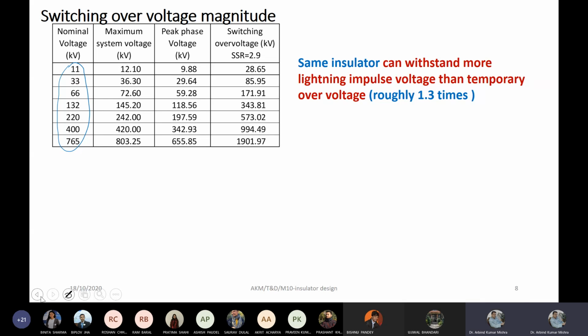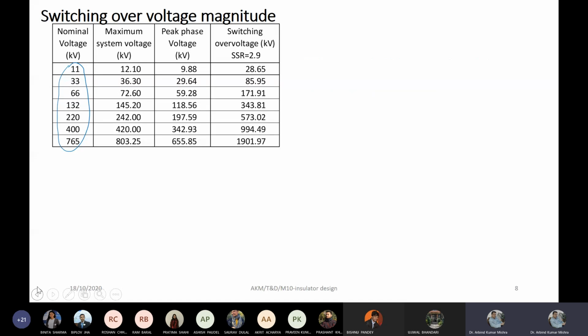as a multiple of the system voltage. So how do we calculate it? For example, for 11 kV, just multiply it by 1.1 and you will get the maximum value. Then you have to find its peak value. Since this is a line voltage, divide it by root 3 to get the phase voltage, and multiply it by root 2. Now this is your E, which we are considering because we can never leave out this maximum system voltage. This is the E we discussed in the last two previous slides and in the simulation. This value is the E, right?